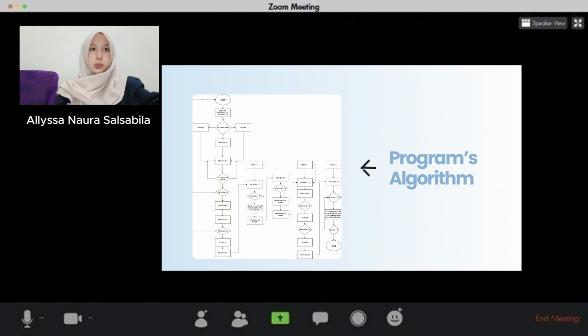The robot will start by initializing the 3 variables, that is, pattern, intersection, and checkpoint, to 0. After that, the line sensor will detect: if sensor 1 and sensor 2 are high, it will turn left. If sensor 4 and sensor 5 are high, it will turn right. And if sensor 3, or sensor 3 and sensor 2, or even sensor 4 are high, it will go forward. And then the robot will follow the line.